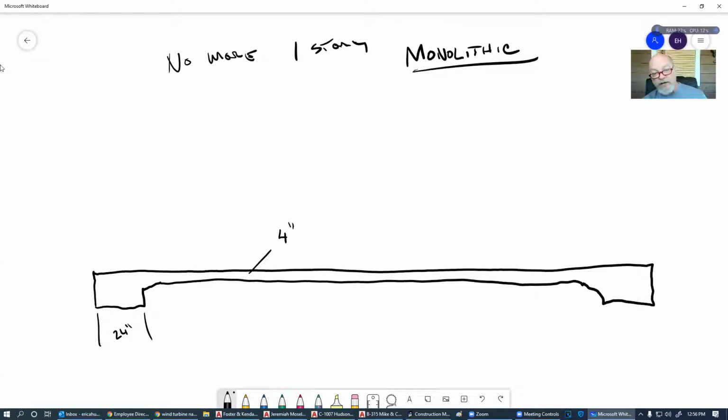If we've got a fire station that's going to have a lot of heavy trucks on it that are full of water, then we're probably going to go to about 8 inches. If we've got a concrete company where we're going to have heavy concrete trucks running across it, 8 inches. So depending on what's going to be on here, and you and your spouse and your kids, 4 inches is about as bad as it's going to get.